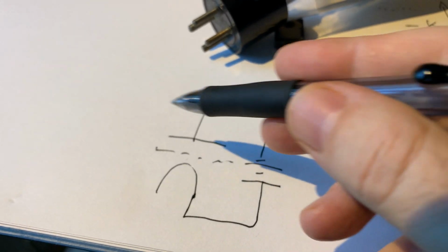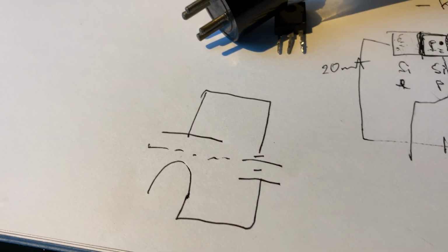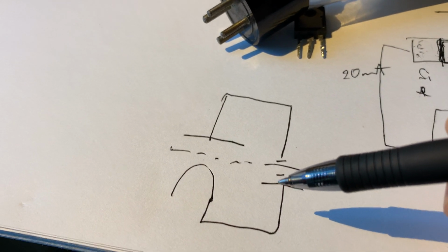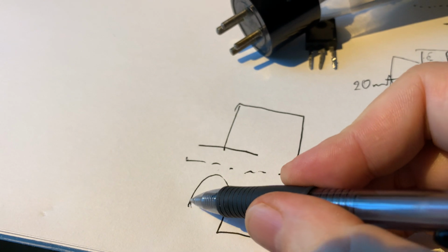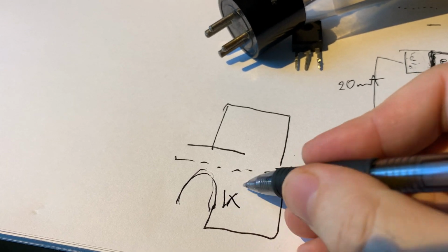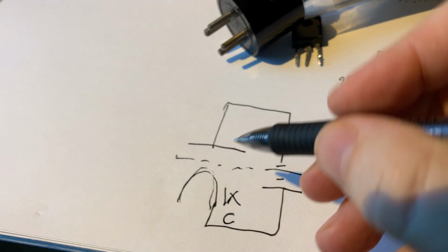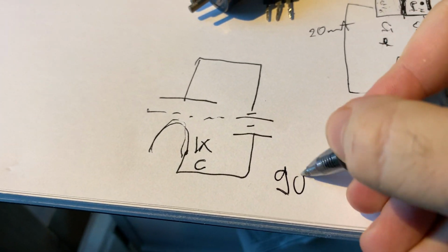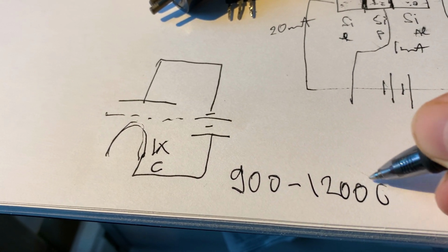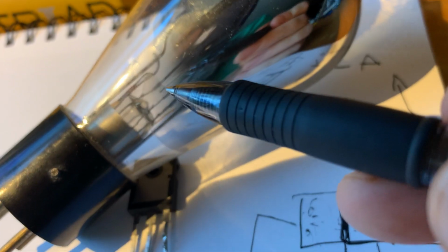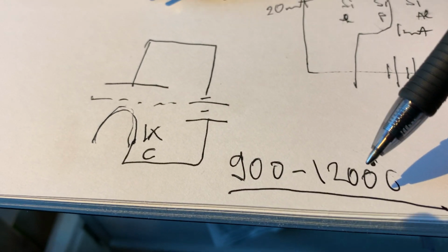So how do vacuum tubes achieve this phenomenon? First of all, it all happens in a vacuum, but to do that, we need to heat up the cathode, usually shown by a letter K or letter C. We have to make it really, really hot. How hot? Between 900 to 1200 degrees Celsius. You see that rod running in the center, it has to be around 1000 degrees Celsius.